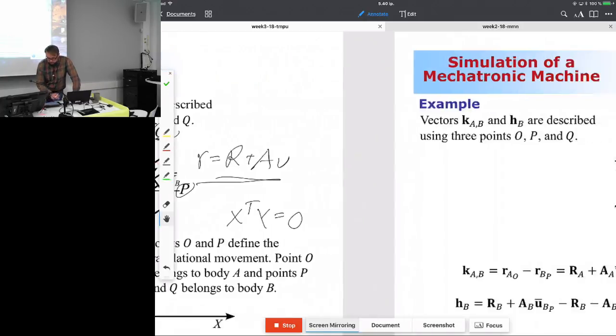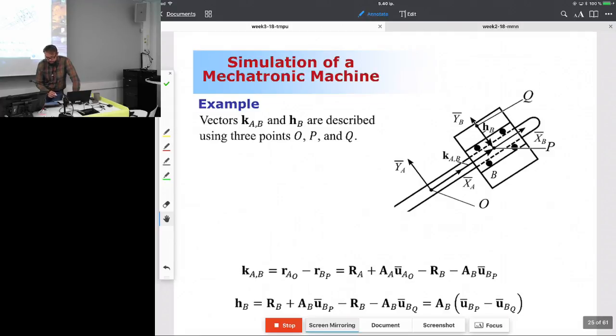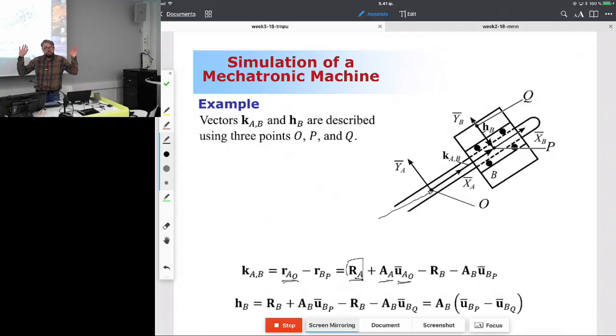So let's define the point O in the very beginning. The point O is defined here. So this is point O. To make that happen, I first have to travel to the body reference coordinate system of body A. All right? So that's this component. Then I'm accounting for the orientation of body A, the 2x2 rotation matrix, and the vector U bar. I really don't know what the numerical values are. I don't care this time. So it's just the vector U bar.